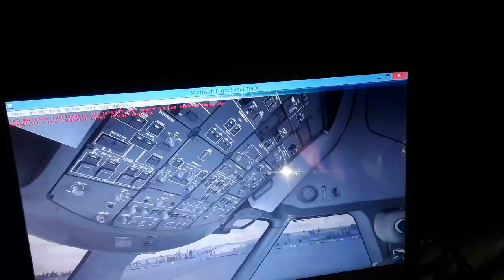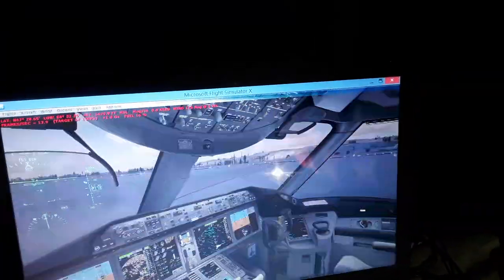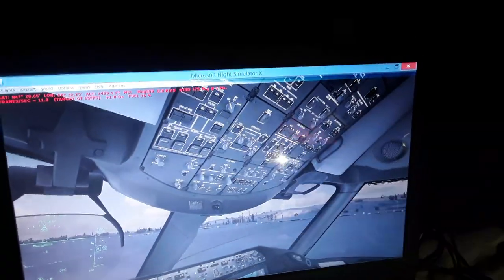Also we have pressurized duct air from the 5th and 9th stage, and the bleed air from the front fan, the bypass air. So we have pressurized air for cabin pressurization. When we climb and descend, we pressurize the cabin and regulate the oxygen. Also wing and engine anti-ice, air conditioning, and ventilation, and also hydraulic fluid tank pressurization. So we have pressurized air coming from the engines, or from the APU if we need a backup, or the ram air turbine if we have an engine failure. So we have pressurization for the hydraulic fluid tanks over here for the hydraulic system.